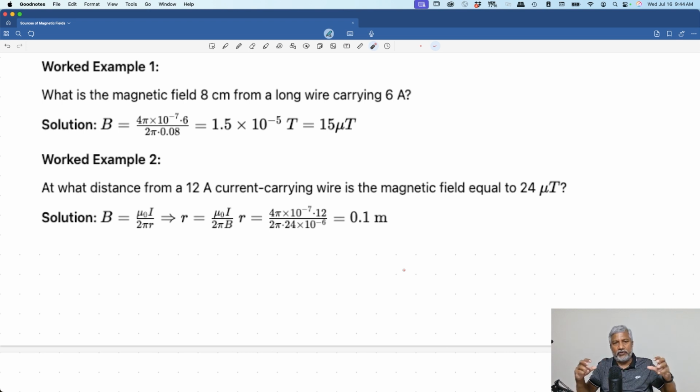Now, what's a solenoid? A solenoid is an extended coil. So if you have something like a PVC pipe, cylindrical, of course, and you have a cable wound on it with the turns touching each other, but the turns are insulated from each other. So when you look at a solenoid, you might think that the coils of turns are touching each other, which they are, but there is a transparent insulation, so the current doesn't flow en bloc. The current has to flow through each turn of the solenoid.